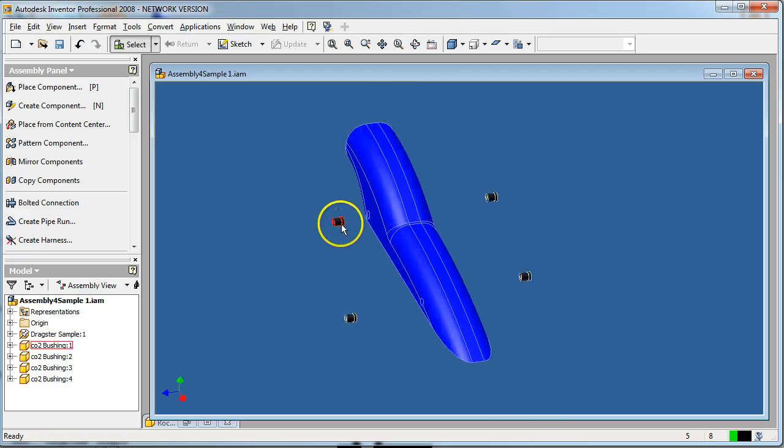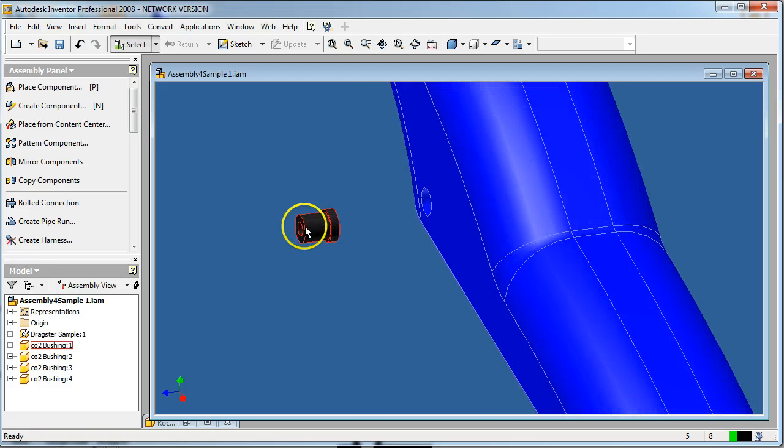So I'm going to zoom in on the first bushing, and I notice that it's not rotated the correct way. That's okay. This smaller part will be inserted into the axle hole so that later the axle will basically sit nice inside the bushing so that there's minimal friction on the axle with the block itself. So the axle will only be rubbing against the bushing on this side and on the opposite side, so that we are reducing resistance here.